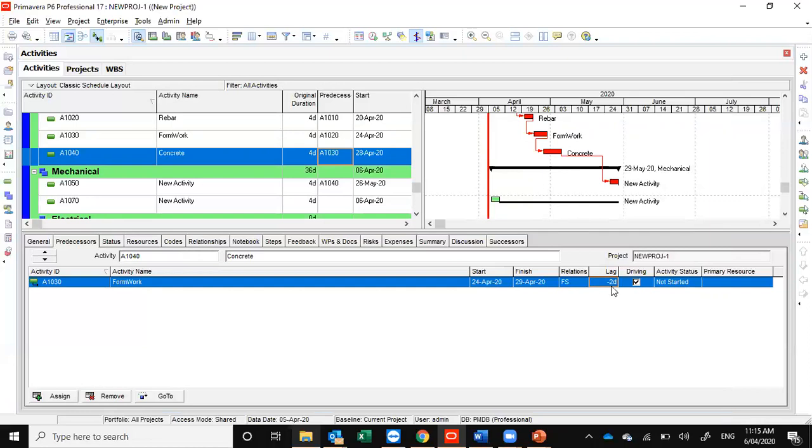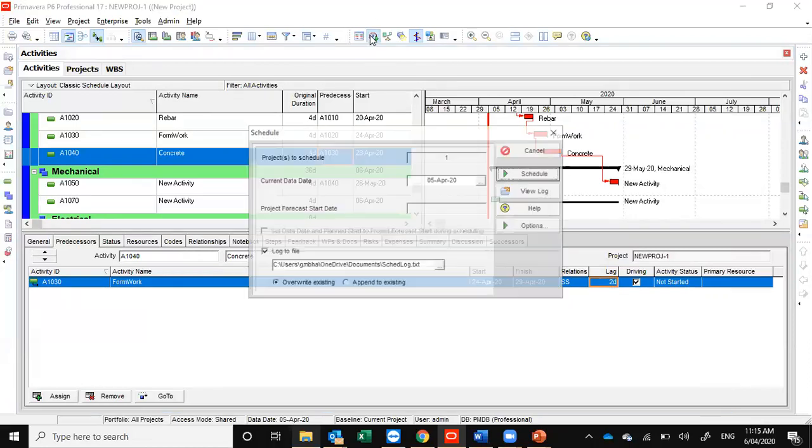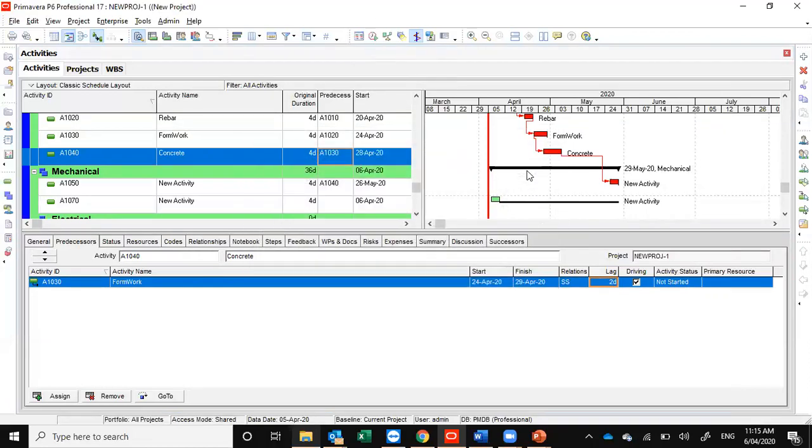Okay, and there is a set of relationship types we have in the predecessor to apply. Like I can apply a start plus lag. It looks similar to finish start minus lead. So it depends on the logic of the program we are making during scheduling. Then somewhere we are using a finish, which means both activities are going to finish; there is no dependency on start.